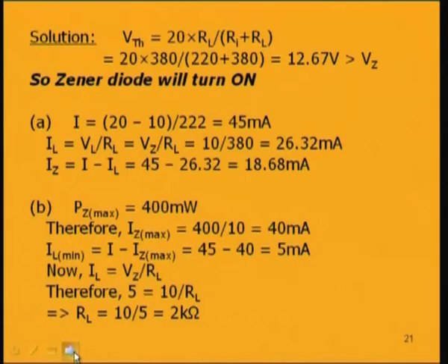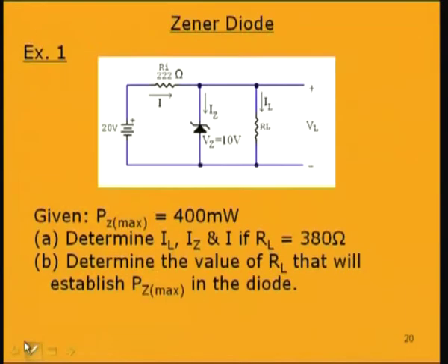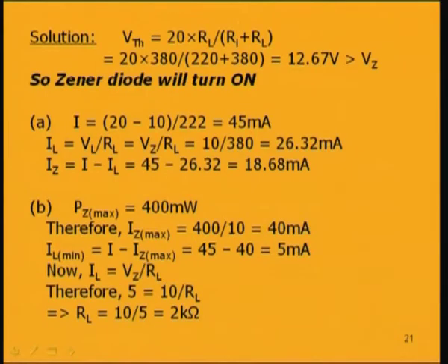So, our next step is to find this Thevenin's voltage across this Zener diode. This voltage we will find after open circuiting this Zener diode. So, next we will be open circuiting these 2 points. Here this is the resistance Ri and this is the voltage 20 volt, and across these 2 points, what will be V Thevenin? You have a resistance RL.